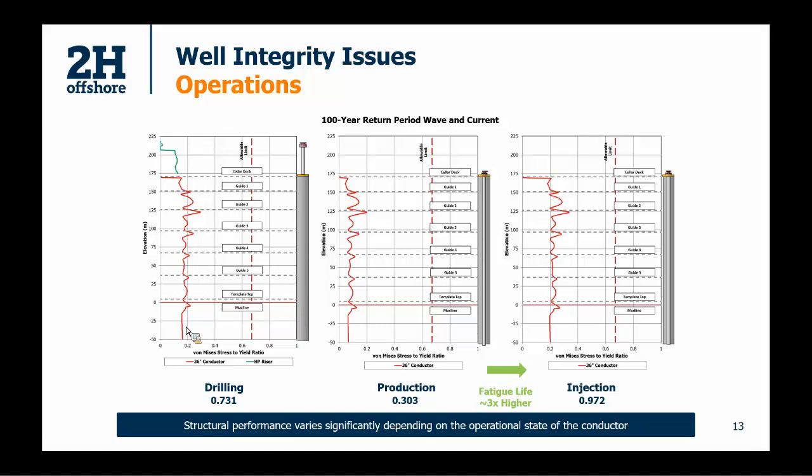What is appropriate is to consider the drilling for the drilling duration, and then to consider either production or injection for the durations that you'd expect those to occur. And for fatigue, we don't want to look at the most extreme event. It would be very tempting to consider production and look at the highest temperature. However, because it's the thermal effects, that would actually be under conservative. You should look at not necessarily the production that you see in the first few years, but the production rates and temperatures that you'd expect to occur for most of its life. So for fatigue, we want to look at the average kind of conditions.